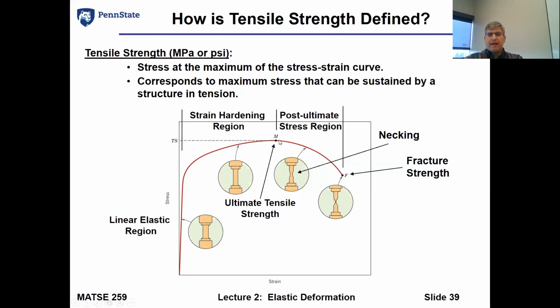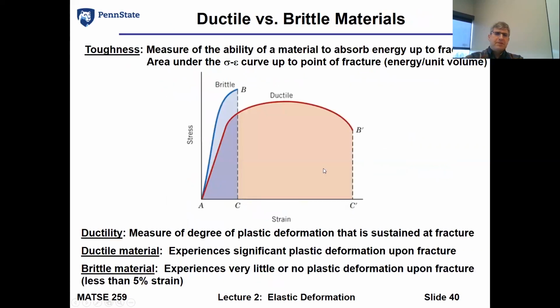And as we reach our maximum, we reach our ultimate tensile strength. But as we go past that, we see the stress start to decrease. And what's happening here is that we start producing a phenomenon called necking, where we have a localized thinning. If we remember our initial videos, the change in length of the piece of rebar, we saw the necking occur prior to failure. And then what we will see is the ultimate fracture or failure of the part, where it will break in two.